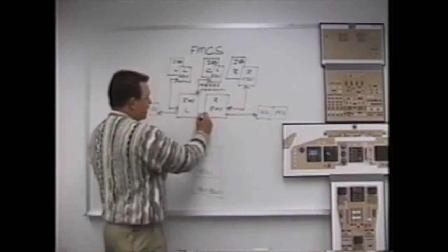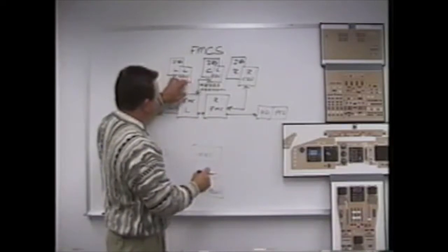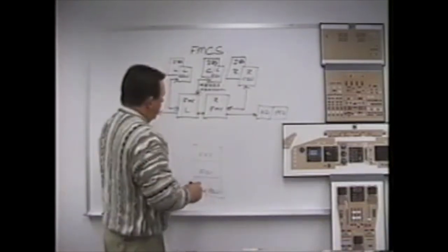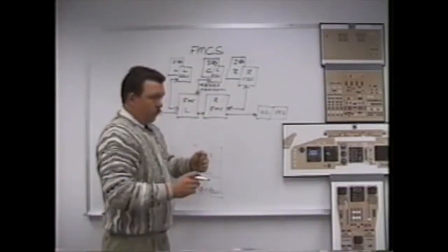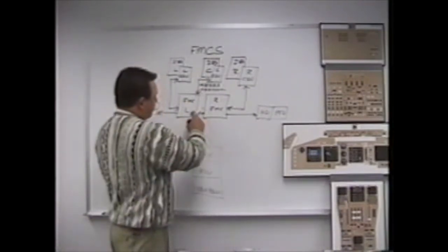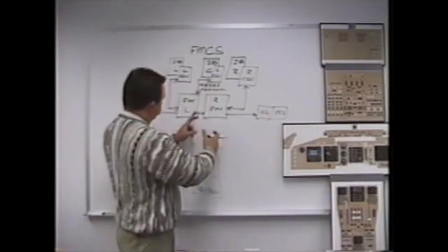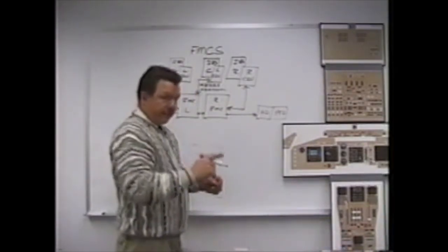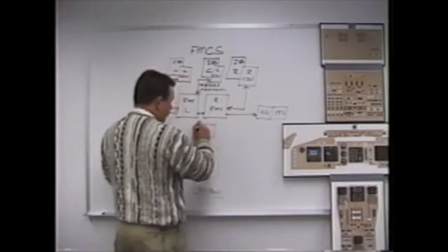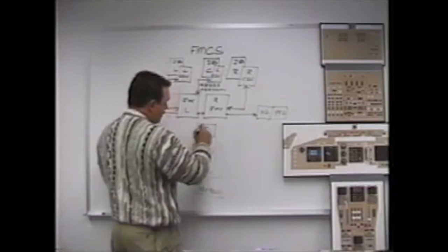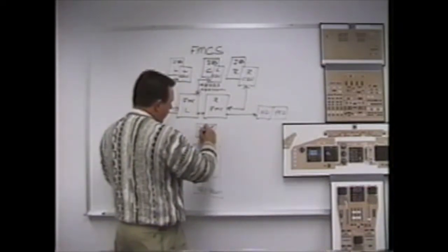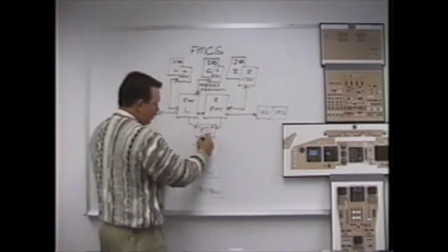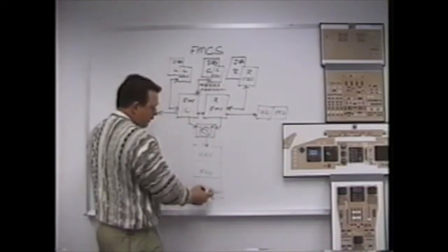These 2 FMCs, again, share information. So if you put something into the left CDU, which stores it in the left FMC, it appears in the right CDU through this signal flow. Like the captain and the first officer, both pilots are qualified to fly the airplane. So the left FMC is just as qualified as the right FMC to fly the airplane. But only one actually gets to control it. Which FMC will control my airplane systems? That's through the FMC master selector on the center panel. Everything being normal, we typically, per SOP, select the left FMC, which gets to talk to my EECs, my flight control computers, and my nav radios.